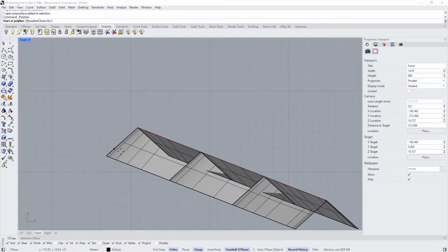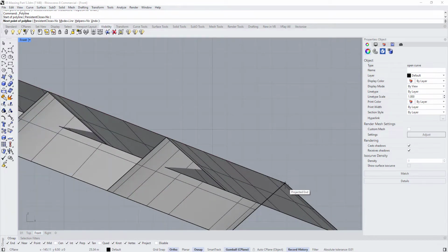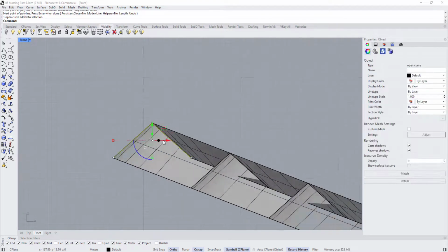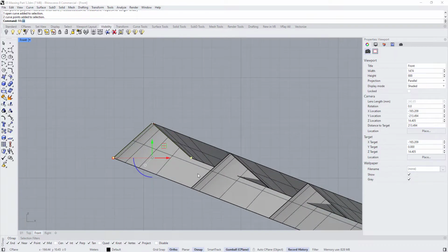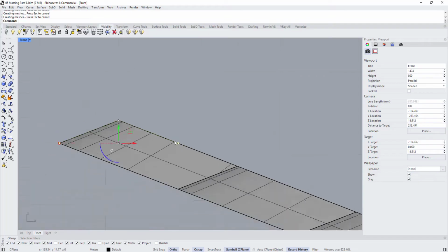To be able to eliminate it, the slope of the roof should match the same height difference. These lines, as you can see, let's open the project and draw a reference line like this, connecting the four roofs together. To eliminate it, we can adjust the slope of the roof. Let's type move and press tab to fix the movement in this direction, and snap it until it intersects with the line that we just drew.